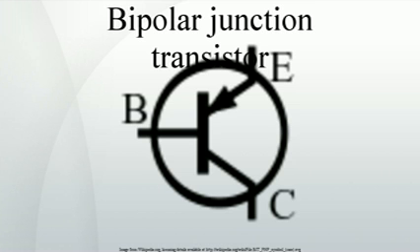Microalloy transistor, MAT, high-speed type of alloy junction transistor. Developed at Philco. Microalloy diffused transistor, MADT, high-speed type of alloy junction transistor, speedier than MAT, a diffused-based transistor. Developed at Philco. Post-alloy diffused transistor, PADT, high-speed type of alloy junction transistor, speedier than MAT, a diffused-based transistor. Developed at Philips. Tetrode transistor, high-speed variant of grown junction transistor or alloy junction transistor with two connections to base.